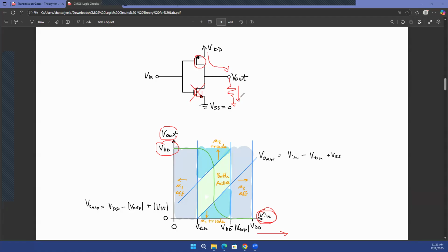So the argument that I made, that in digital circuits you consume energy only when you are switching, is not true if your load is a resistor, because you'll keep on drawing current. Only if your load is a capacitor, then you just charge the capacitor, and when the capacitor is charged, you stop drawing current. There's no point drawing any current if the capacitor is charged, right?